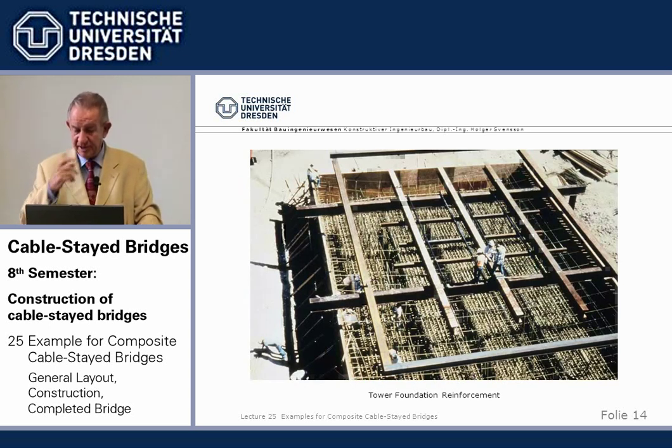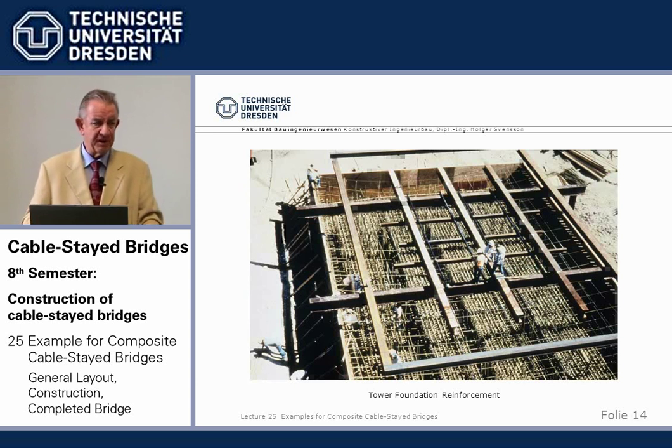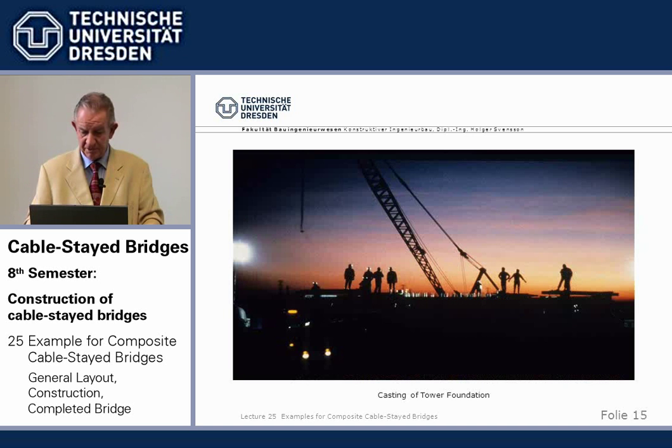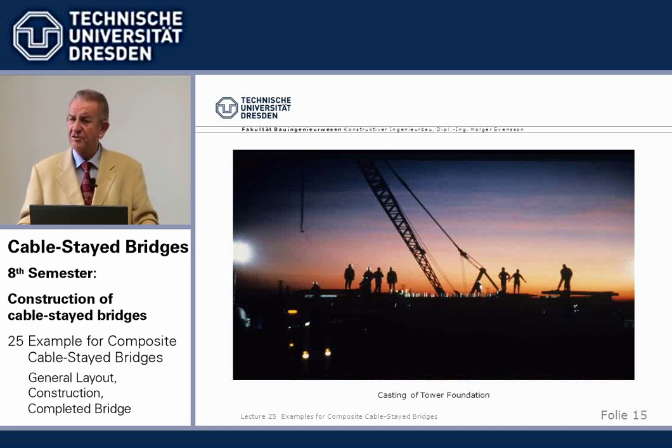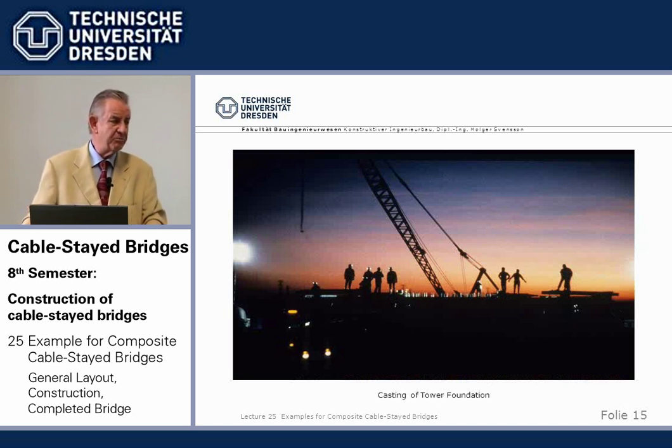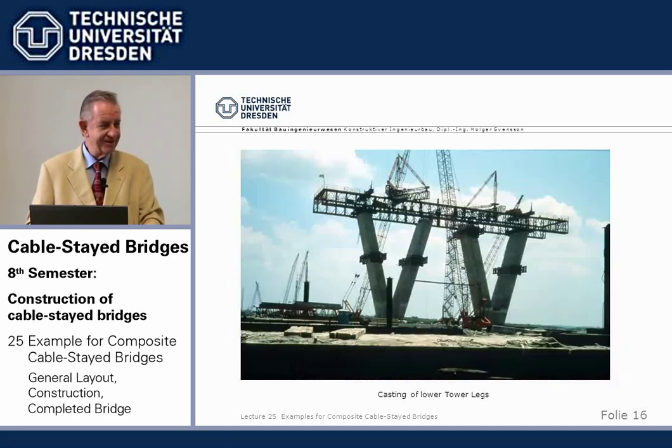It goes on then, heavy reinforcement, 40 millimeters, which I personally don't like very much. The end connections are questionable, but that's the way you do it in the US. And then we had more than 1,000 cubic meters of concrete per pile cap, cast, of course, in one go, 24 hours a day, and that gave us this nice photograph.